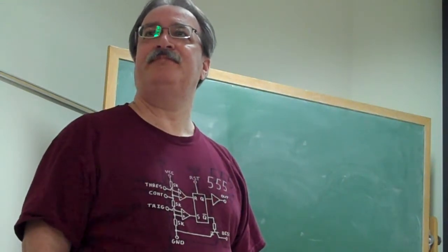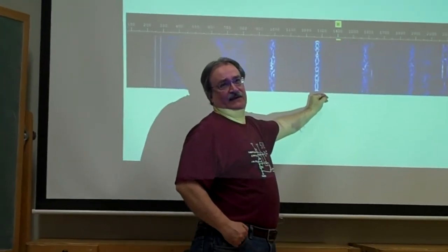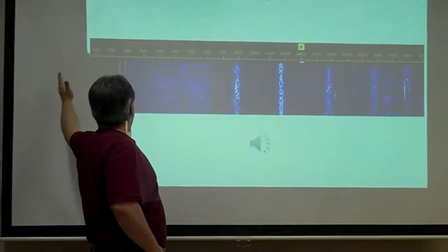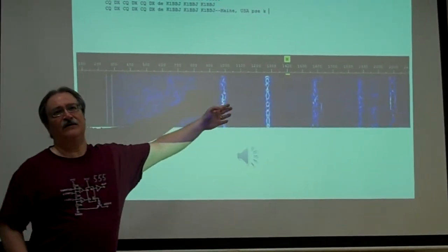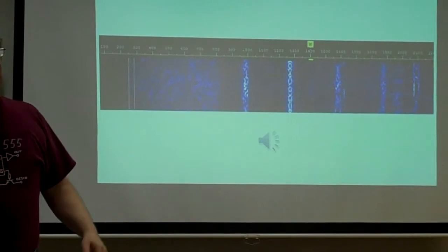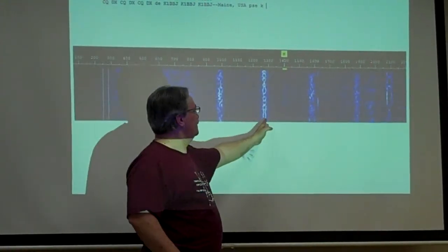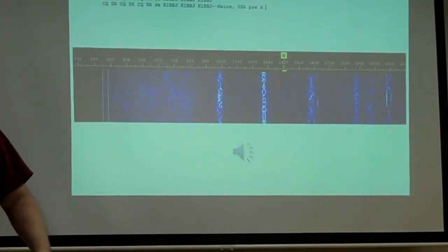So the width of the waterfall is the 31 hertz? No, the 31 hertz is the spacing here. That's your 31 hertz, just the width of that line in the waterfall. And the 2500 goes all the way from 0 all the way up to 2500. And that's why so many of those QSOs or channels will fit in that 2500 hertz band.